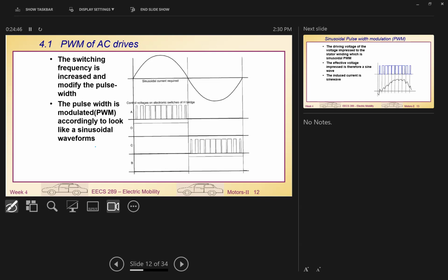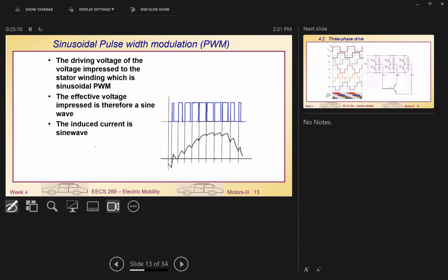We use the duty ratio to make it look like more voltage. In here, we use a smaller duty ratio to make it less voltage. So it still looks like a sine wave, but using the pulse width to emulate a sine wave. That's good enough for the motor. The motor doesn't understand what kind of waveform we put in, it only knows the average voltage.